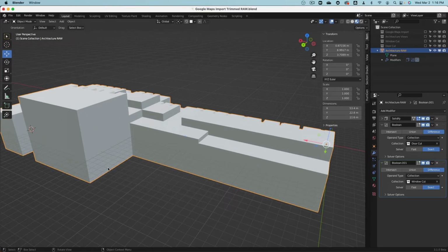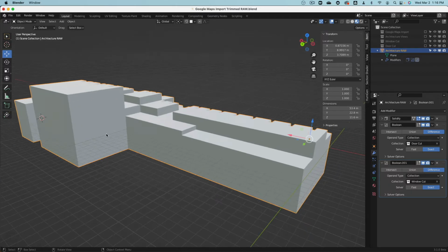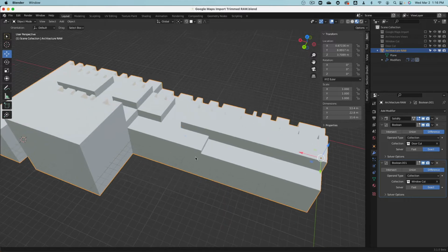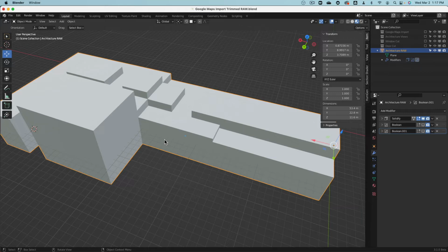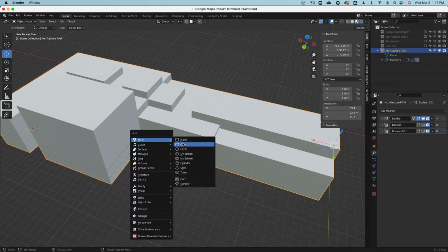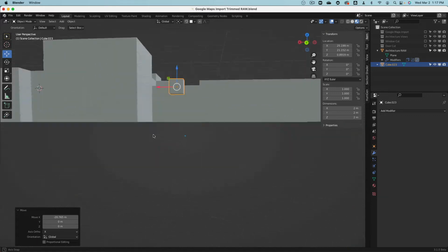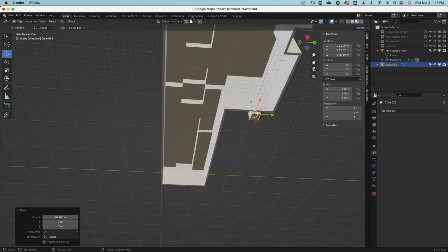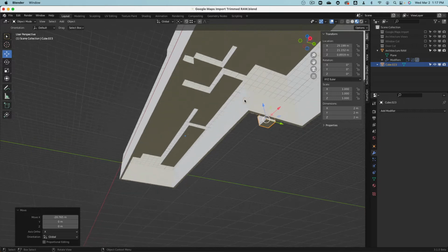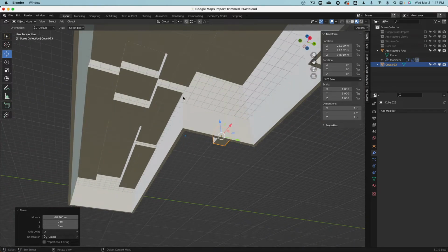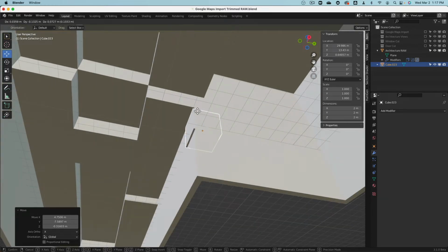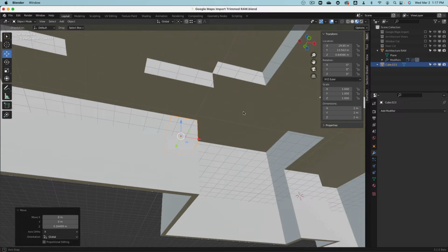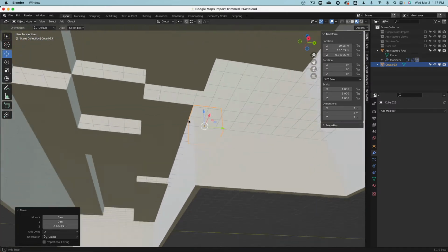So now we need to generate also the cut for opening this part of the space. So let's see how we can do this. These two I hide for the moment. Shift A, and I will add a cube. This cube I will move to here. Actually, I will go to point snap and then snap this point. G, hold control, right? No, not there. G, there. Okay, yeah. There you can see where it sits right now.